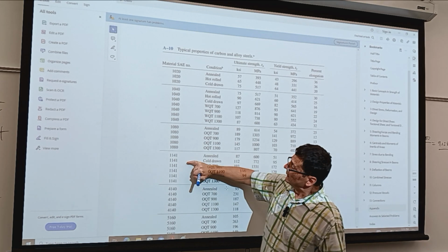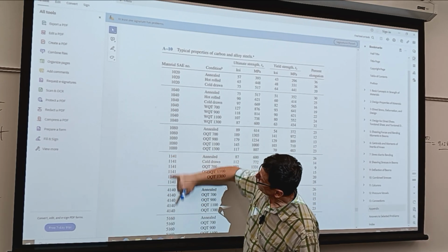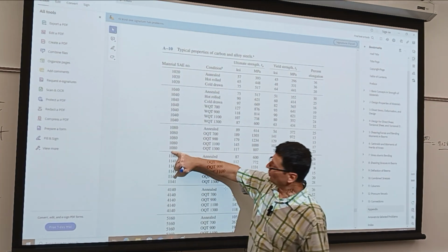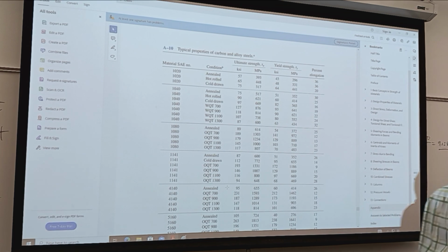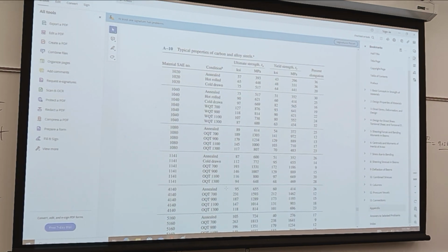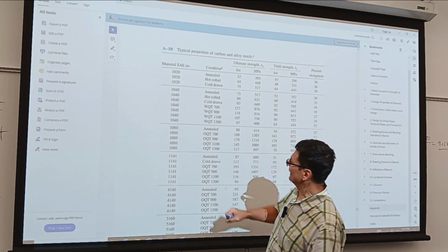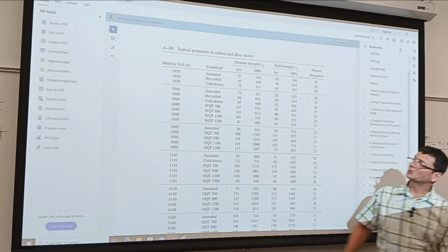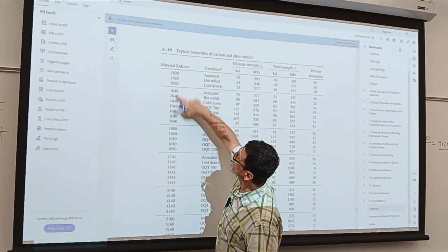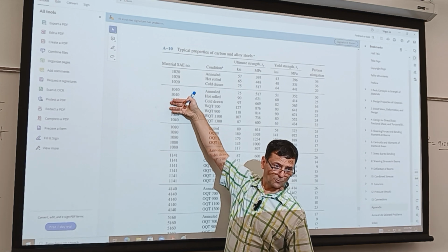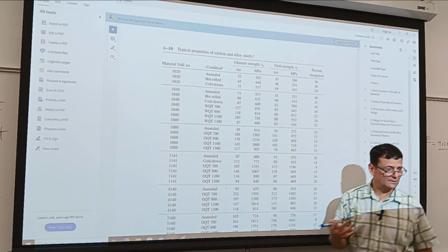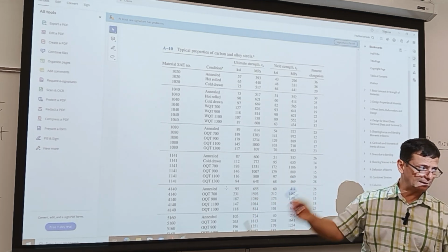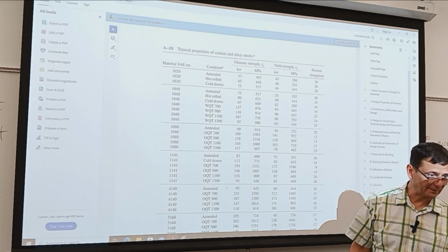All right. Now these start having numbers on the second digit. So they're alloying elements, and those could be chromium, manganese, other types of alloying elements. And why is that? Because they improve hardenability. What does that mean? You can achieve the same hardness as the plain carbon steel, but with less severe cooling. So instead of dropping it in water, you let it harden in air.